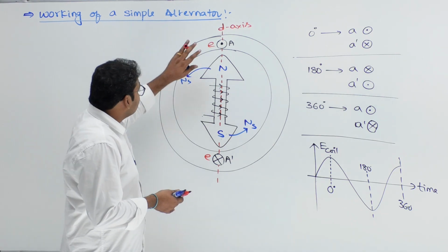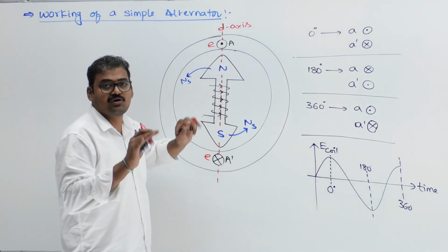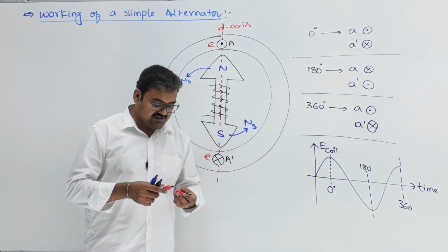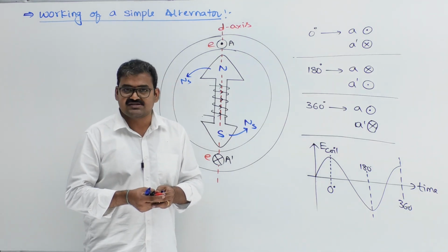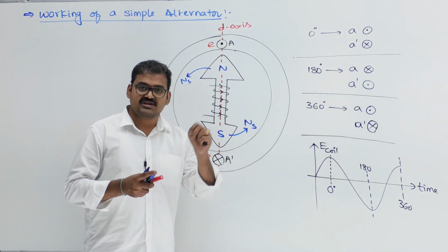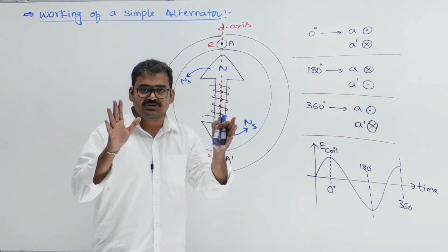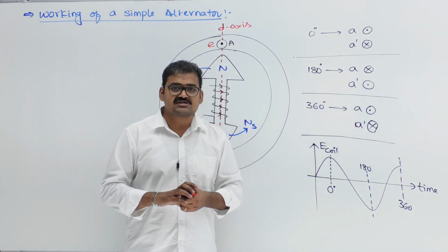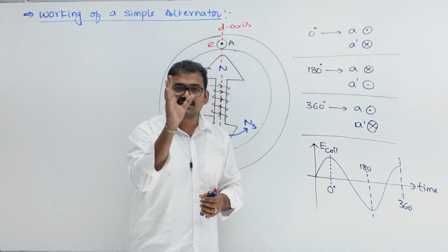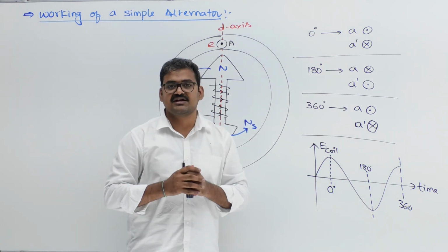This is the simple observation having only one coil. Assume that it is a phase A coil. But a practical synchronous generator will always be designed for one phase or three phases. Now let me consider a simple alternator with three phases A, B, C. Our requirement is that a balanced voltage has to be generated. What is meant by balanced voltage? Balanced voltage means there should be exactly 120 degrees phase angle displacement among the three phase voltages.